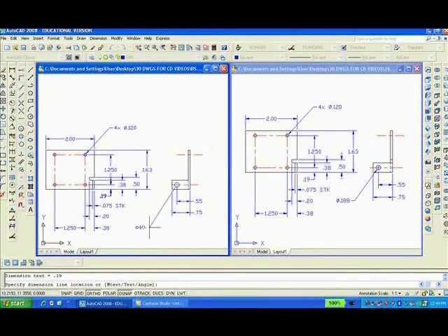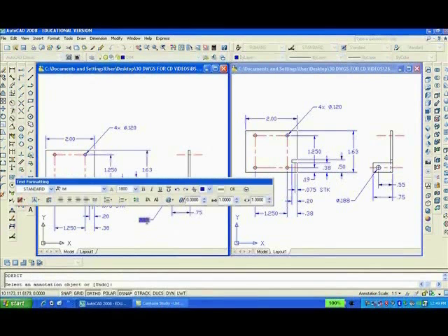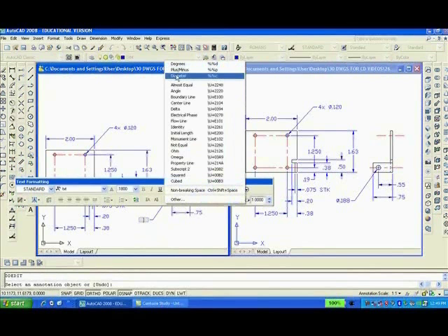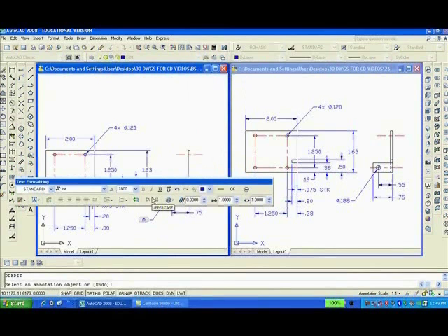Click the circle, drag it down here, and it says 0.199. Well, I better change that. So I'm going to edit, ED, enter, and I'll delete it. Delete, and I'll go here to symbol, put a diameter, and then 0.188, and click OK.